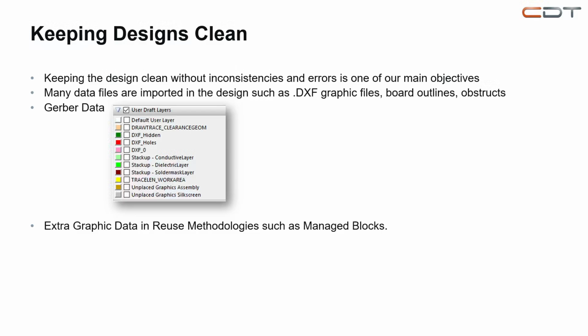Once you finish with the pre-design preparations, try to clean it. As a very specific thing, if you use managed blocks, they also can contain unnecessary extra graphic data, and in this case you need to change the managed block itself. It cannot be done directly in PCB, in layout I mean.